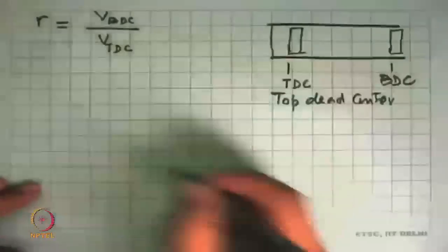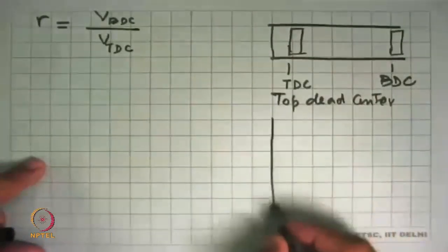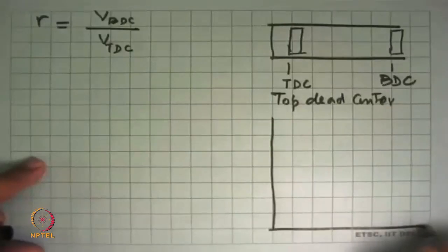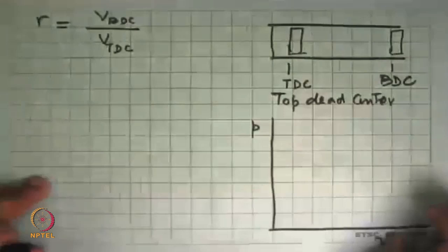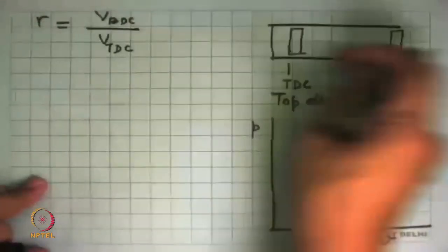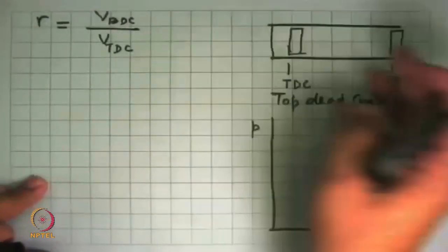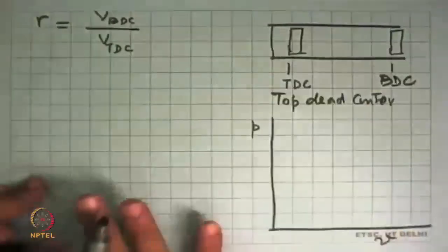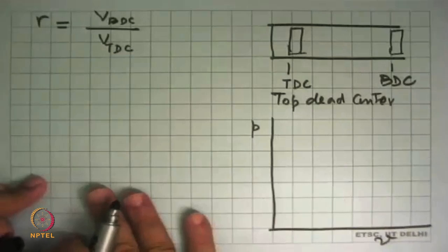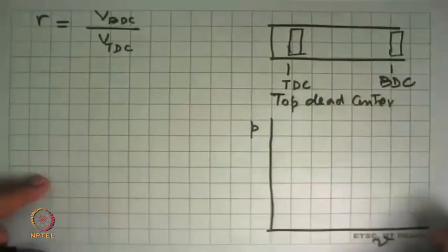And if you look at the complete analysis of this cycle, the air standard Otto cycle will look like this. I am plotting V here and pressure here, and we ask, when the piston goes up and down, how does pressure vary, what is the heat transfer in each process, and what is the work transfer in each process. This is what we want to know.